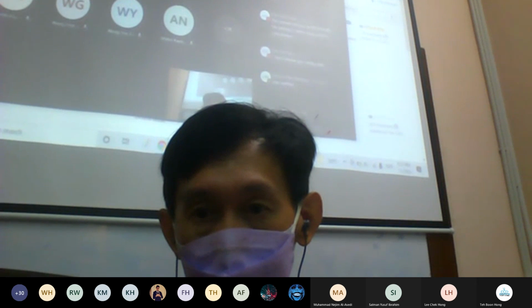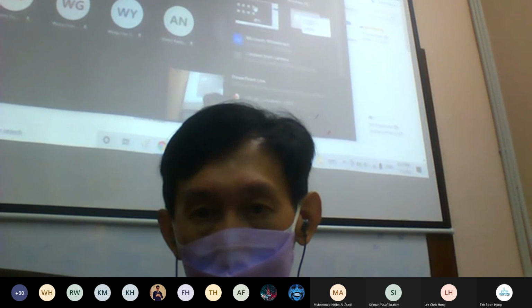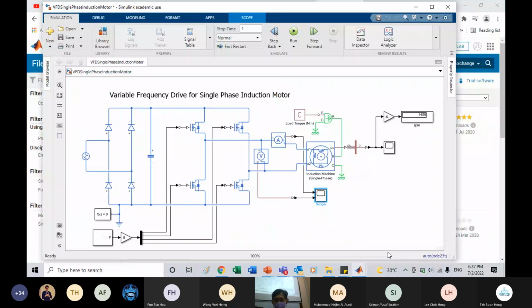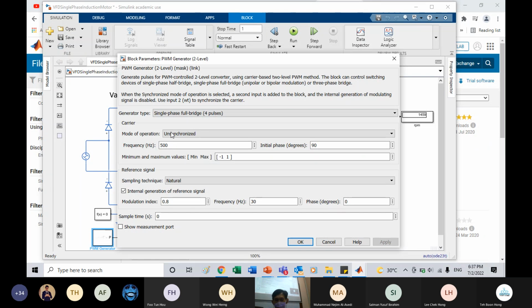Wait, I share the screen again. Okay, can you see my screen? Now you see the modulator appear. This frequency is the switching frequency, 500. And this frequency is the frequency of your sine wave, where you want to control the speed of your induction motor.